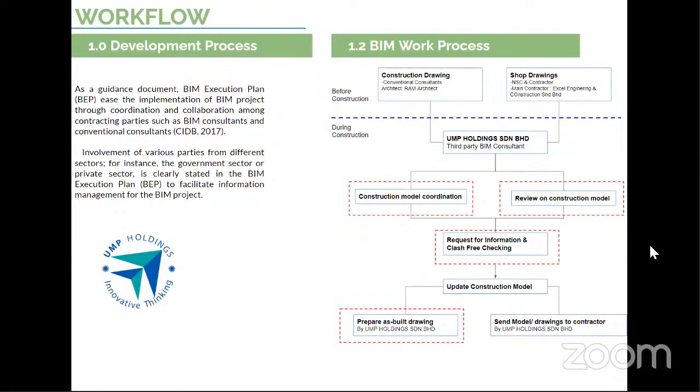During construction, the BIM company runs through the construction model coordination and reviews the construction models. Following that, they will run through a request for information if there are missing items, and also clash-free checking. Then they will continue with updating the construction model as well as preparing as-built drawings. The ones highlighted in red are the processes that involve the coordination of workflows. Next.